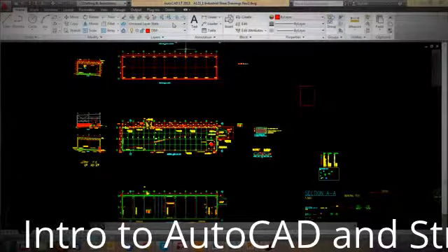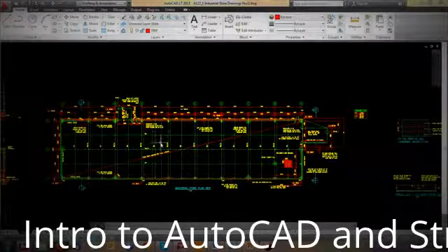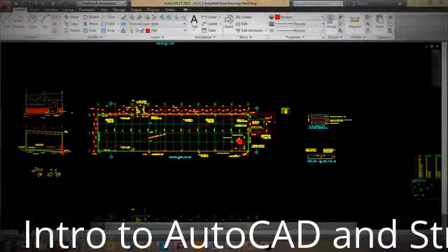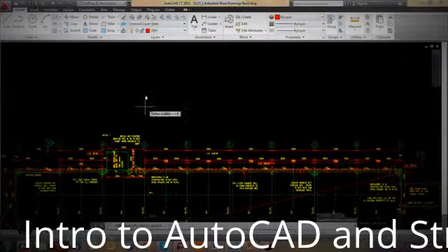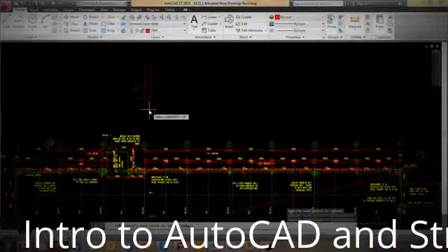Then, there are command lines, the way AutoCAD used to be used more, but it's still a very useful tool, and especially faster draftsmen like using the command bar, this bar at the bottom here. If I want to draw a line from the ribbon, I'll just click line and draw it. Press escape to stop using it.